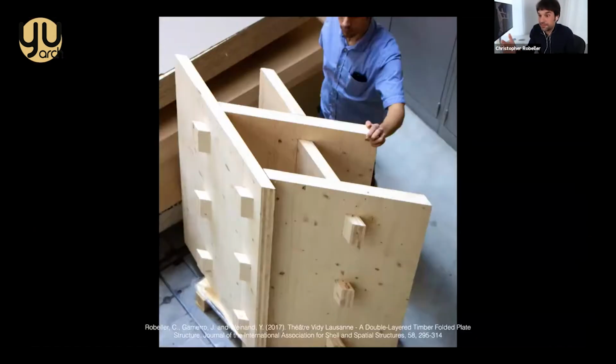But yeah, I mean, it gets really interesting once you take it to a building scale, because making little models is one thing, but really making a building is a completely different story. So that was a fantastic opportunity for this VD Theater project to really take it to full building scale. And in this case, it meant 5 centimeter thick wood plates, CLT. And this was the first prototype that we made. And you can imagine that you have some certain imprecision of a few millimeters, but you do not want the joints to lose contact.